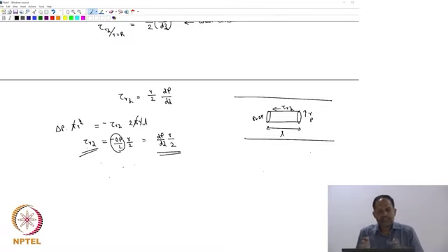Look at this force balance. This force balance tells that any fluid element you are going to see experiences a force because you have applied a pressure from one side. So, the fluid element is trying to move in presence of the rest of the fluid, but when it is trying to move in presence of other fluid elements, it is experiencing a shear stress in the opposite direction, because viscosity does not like things to move with a differential velocity. Viscosity will try to resist it by applying a shear stress.